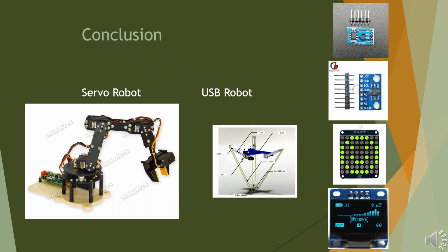Serial communication, with its simplicity, robustness, and noise resistance, has become the dominant approach in modern embedded design. From there, we examined the major wired communication standards that connect hardware components. UART, Universal Asynchronous Receiver Transmitter, a simple point-to-point protocol widely used for debugging and serial interfacing. SPI, Serial Peripheral Interface, a high-speed, full-duplex protocol suited for sensors, SD cards, and displays.